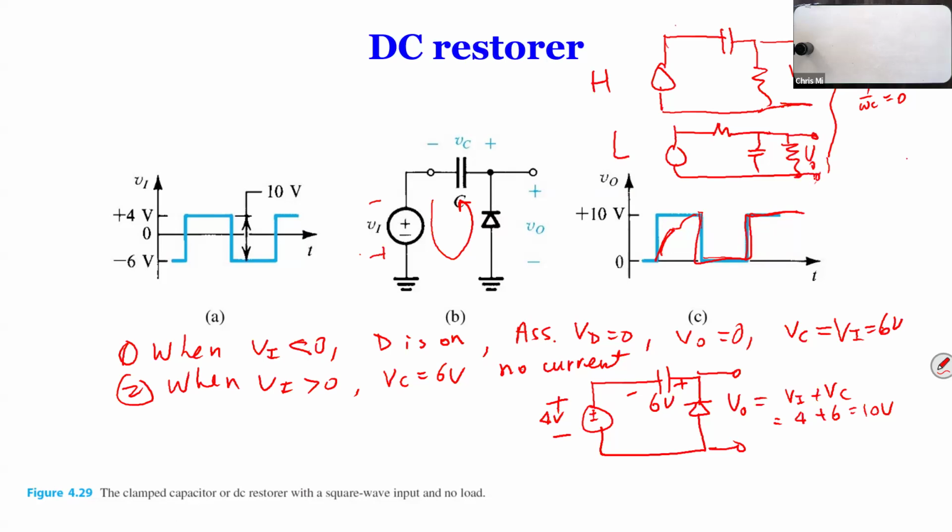With this type of circuit, yes, you can filter some of the components you don't want, but the problem is that you cannot do 100%. It's always going to keep something there depending on the cutoff frequency. The issue is that once we add a load resistance at the output, things are going to change, because current will flow from the capacitor to the resistance.